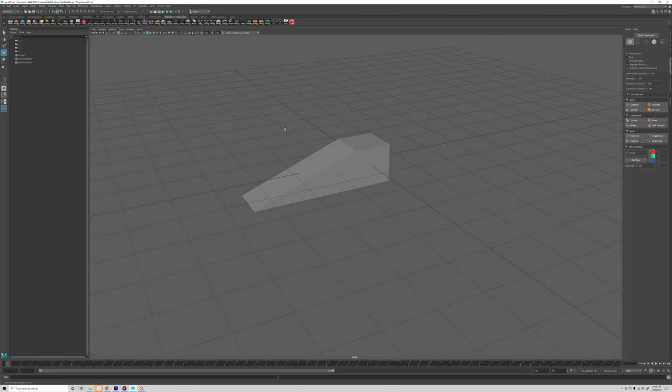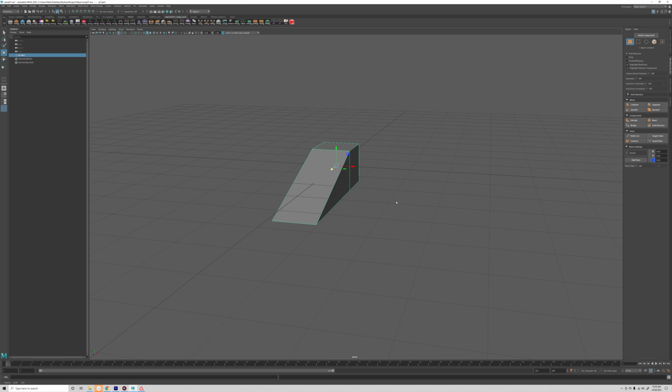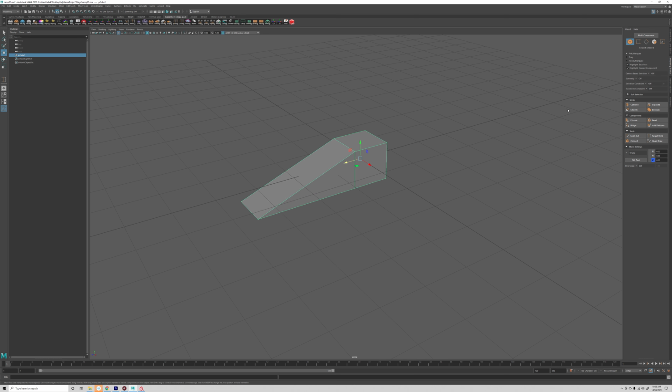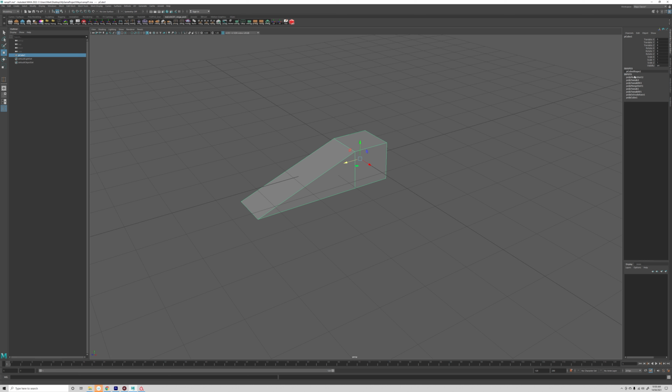So we could obviously do much more complex things, but you know, the whole point of this video is just to show you the workflow, what you need to follow. You can try more complex things later. So I've made my model. Our standard practice, Maya builds up history. So we always want to get rid of that. So edit, delete all history. So we don't have any history there.